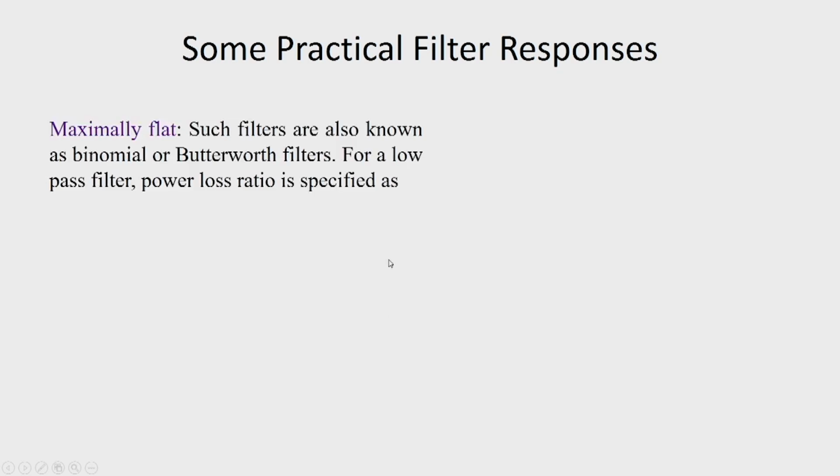Now, this power loss ratio we have written in the form of polynomials in omega square, M and N. Now, let us see some practical filter responses. The first one we consider is called a maximally flat filter. Such filters are known as binomial or Butterworth filters,